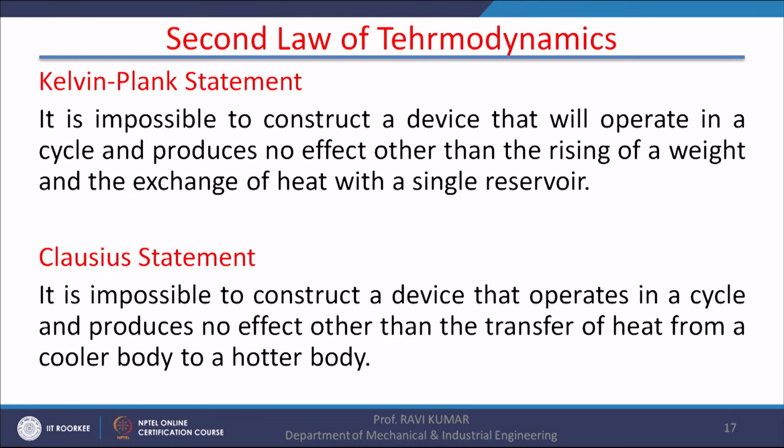Another statement is by Clausius. The Clausius statement says that it is impossible to construct a device that operates in a cycle and produces no effect other than the transfer of heat from a cold body to a hotter body.